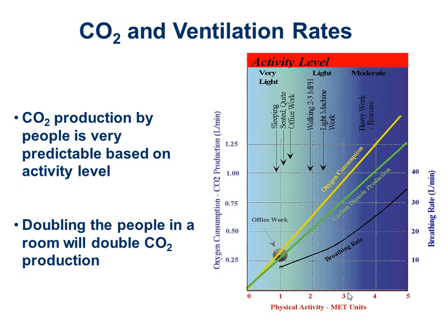However, if you're running on a treadmill or playing a basketball game or something like that, you're probably going to have a metabolic rate of 3 or 4. So hence, we need to ventilate those types of spaces with a higher outdoor air concentration. And the main reason we're ventilating spaces with outside air, at least for the people purposes, is to dilute body odors from people. So it actually works out kind of nice that the more you breathe, the more body odor you have, and those things are linked together. So if we track your CO2, we are getting a pretty good indication of tracking the ventilation requirements.